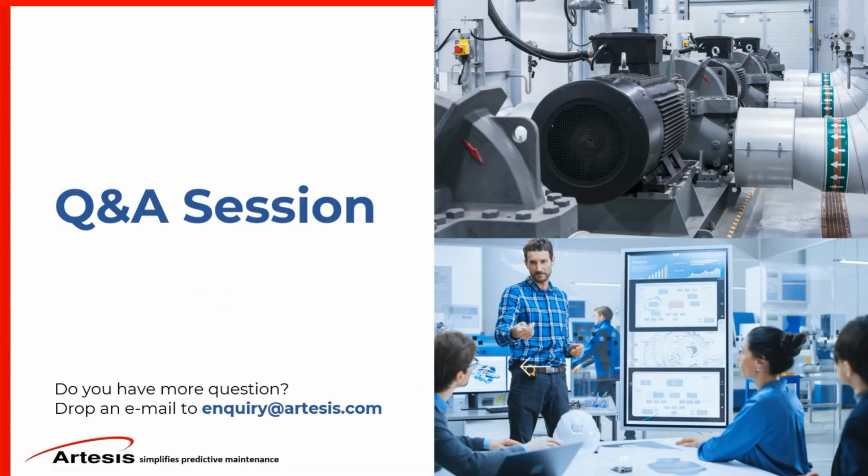How does the automatic diagnostic report generate the normal, caution and high alert zones? Is it based on any standards? This is a question from Gary again. For cavitation, through the pump performance, we are following the system curve, and there are certain percentage deviations from the pump's best efficiency point, which is used as a reference point to detect cavitation.